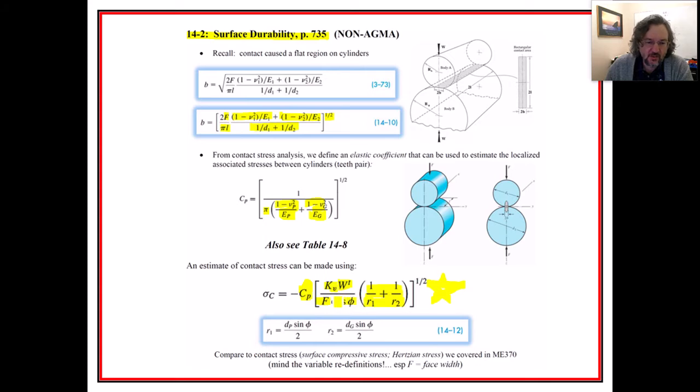They also adjust a little bit for the orientation of the force by dividing by the cosine of the pressure angle, because the force is not just the perpendicular force, not just the transmitted one, it's the magnitudes, because that's the one that's actually running across. If this is the tooth profile right here, the load that's causing contact stress is the total load that's perpendicular to it. So that's what that's all for.